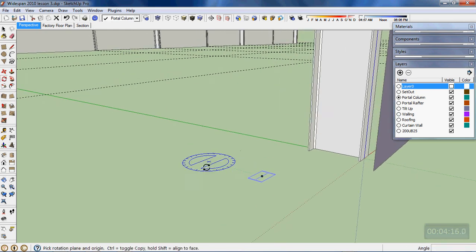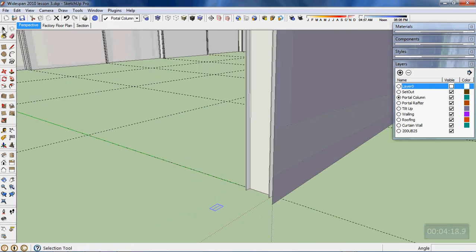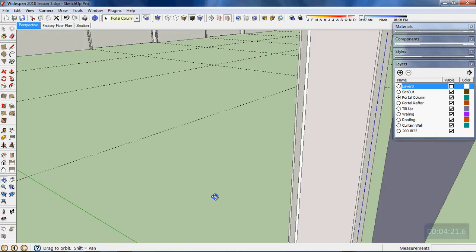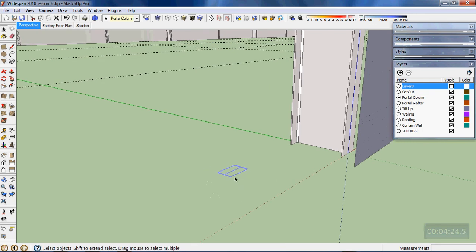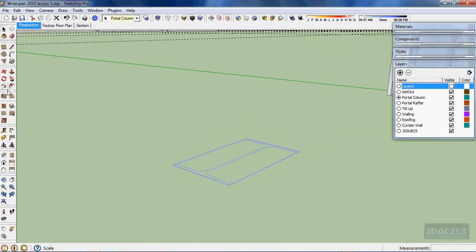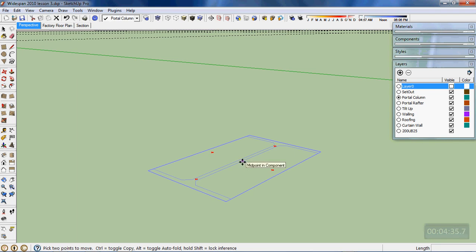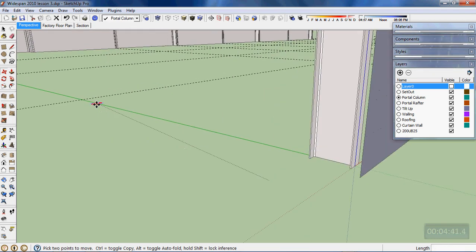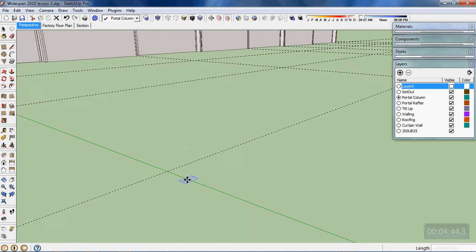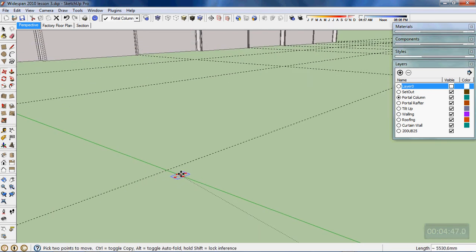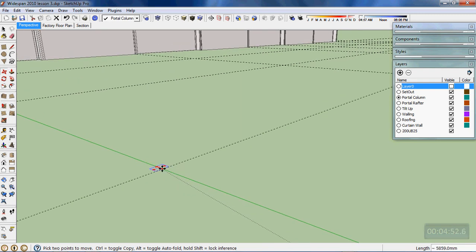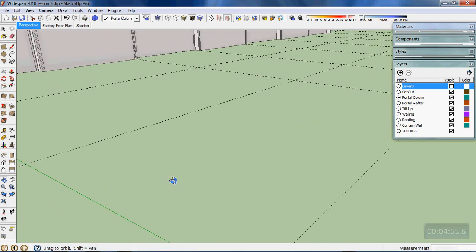Okay, so I'll then pick up that object across and pick it up very, very carefully. First of all, I'll pick the move, and I'll pick up very, very carefully on one of the midpoints of the web member, like I'm doing just there. So one of those midpoints to get the center of it, and then I'll just locate that temporarily along the main grid line. In fact, I might go to the intersection for now, but it won't be quite correct.